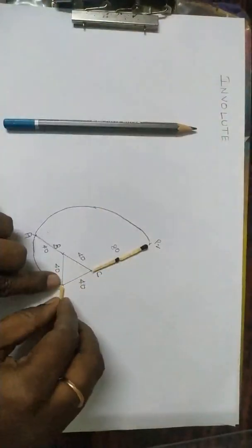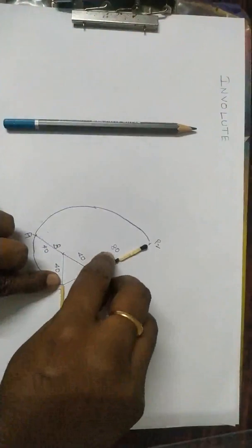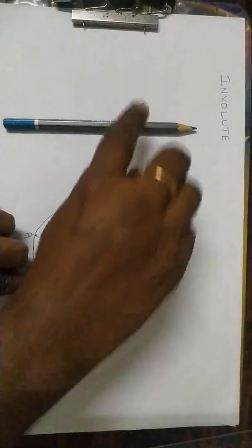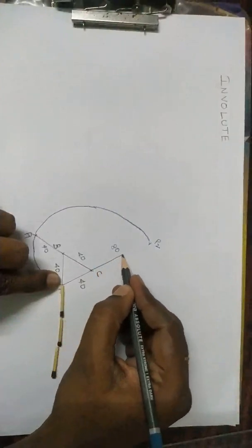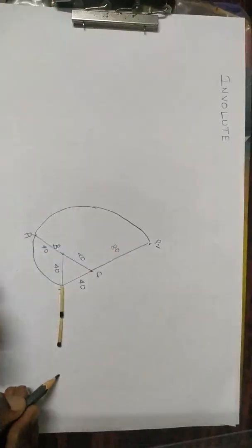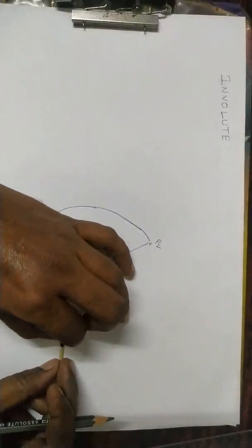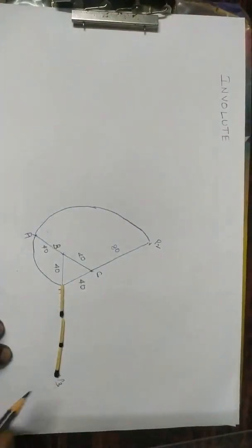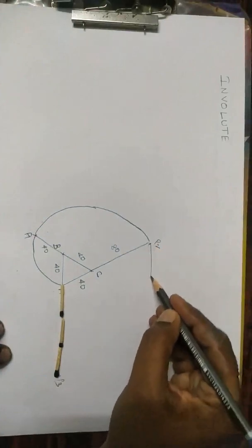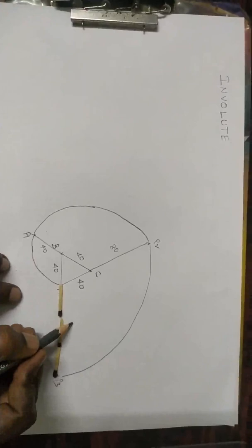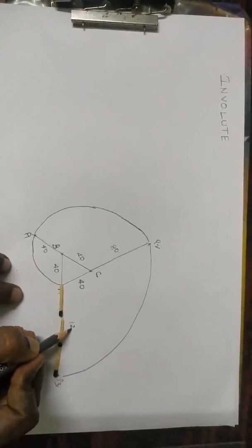This is AB, the straight line. Next. Unwound like this. Okay, and also I have to join this one like this. Yes. And finally, where it comes, this is the end. See here, this is P3. Okay, this is P3. And how it is traveled? It is traveled in this path. Yes, and what is this length? This is 120, 80 plus 40.